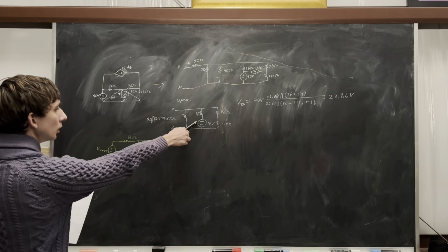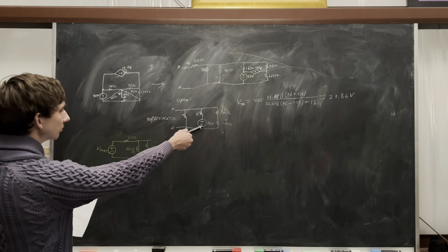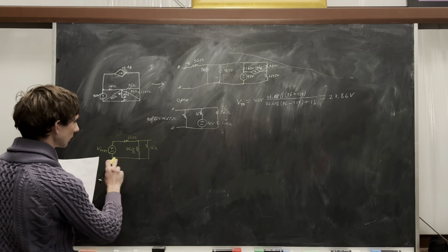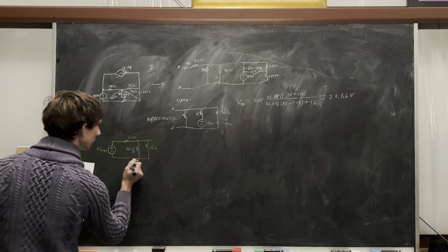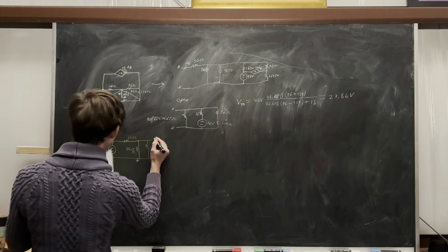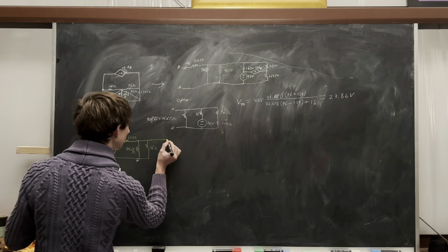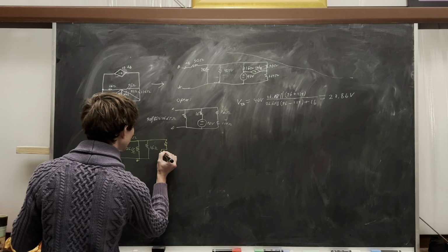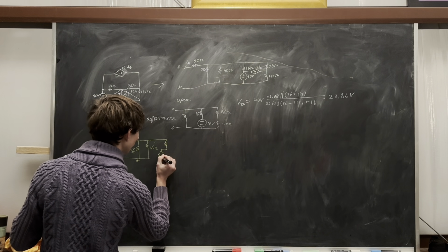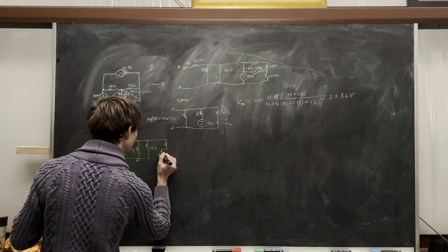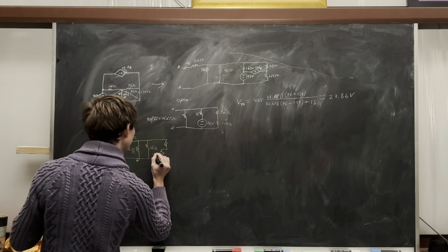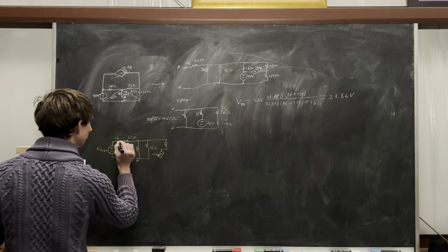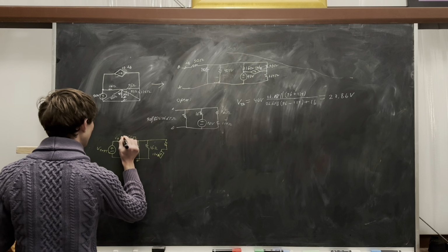I also short out this voltage source because a 0 volt source is just a short. That's why this 16 ohm resistor ends up going to this same ground node here, because we're going to end up doing nodal analysis later. 96 ohms over here, and then we have that dependent current source, 10 IV. We have IV here. We also have I test going the other direction.